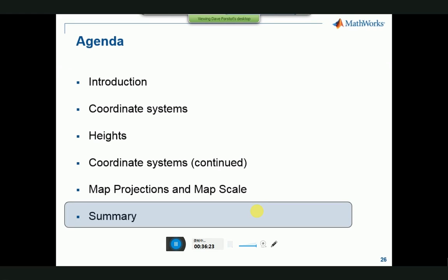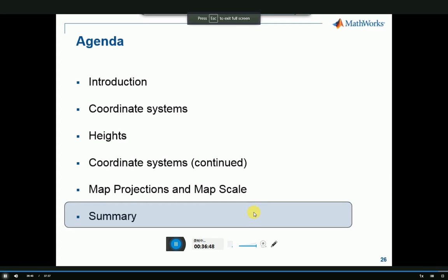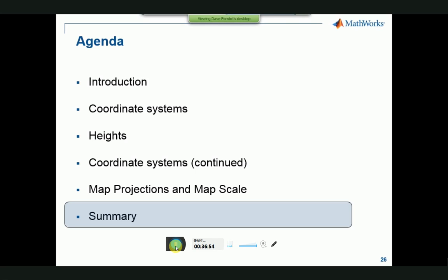So, the key takeaways. There was nothing wrong with the GPS. There was nothing wrong with that map. What was wrong was my usage of two numbers, a floating point value that was valid for latitude and longitude in a specific reference frame, the datum. When you're dealing with positions, it's important to understand what reference system you're using. That's not just the ellipsoid or the datum, which defines an ellipsoid, but also the height. And when you're dealing with projected data, knowing what that projection is and what it's based on so you can move data into and out of it.